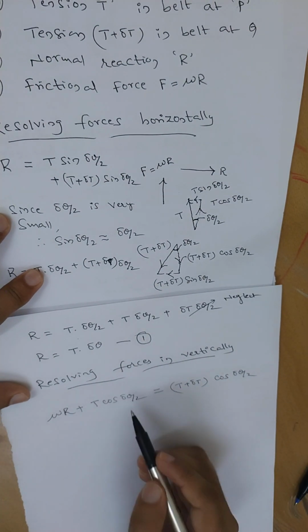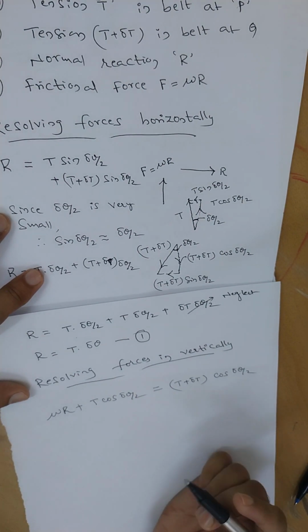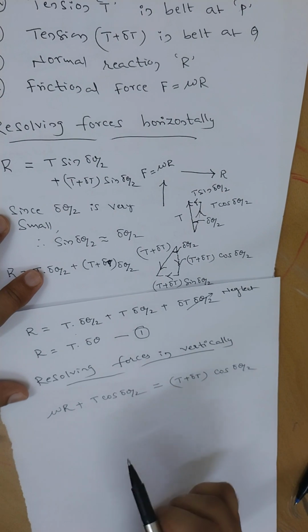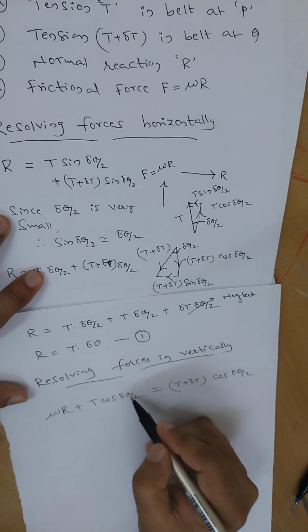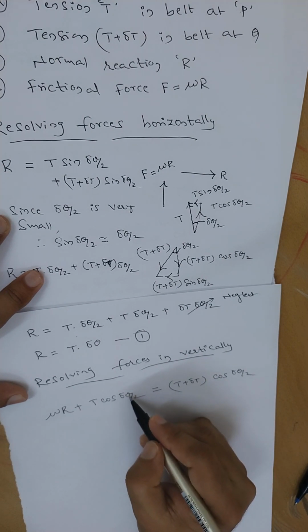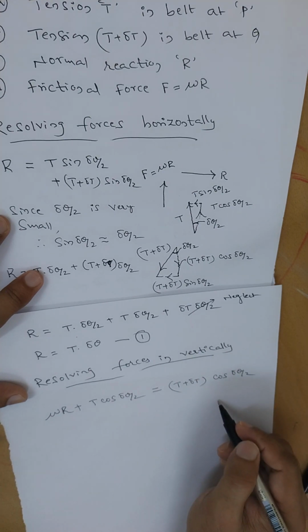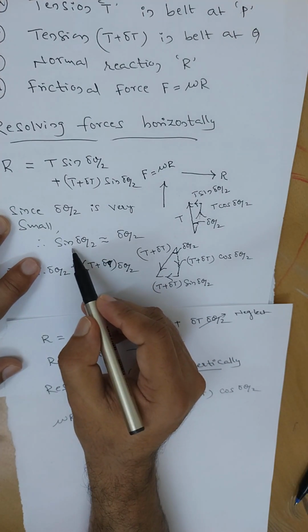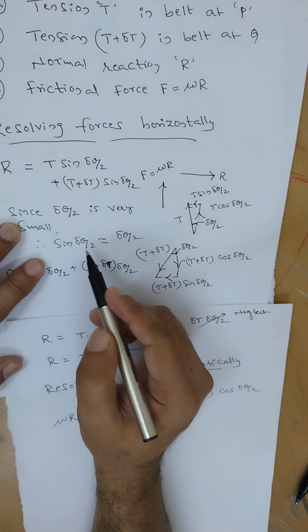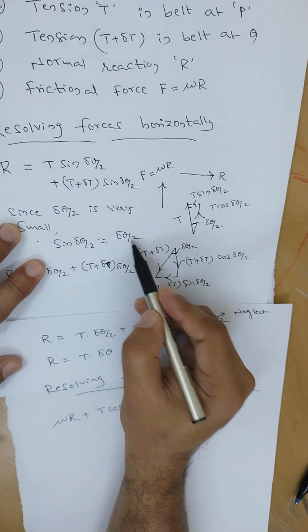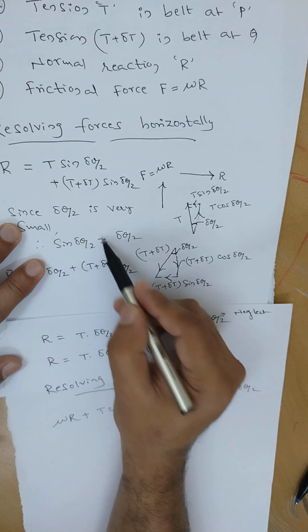Okay. Now again here dθ/2 is small. What will be cos(dθ/2)? It will be equal to 1. Why? Because if dθ is very small, it is nearly 0, and cos 0 is 1. But in the case of the sine component, sin 0 equal to 0, and we should not take 0. dθ/2 is very, very small, but we need to consider dθ/2 as the value.